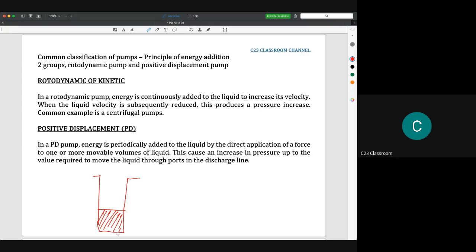So what people do is people do not install a centrifugal pump inside this well. Normally people will use a positive displacement pump. So we have a long pipe here, and then we have a pump here with a jack, with a handle like this. I think you could imagine this one. So when you move this handle up and down, it starts to suck water here, and finally the water will come out.